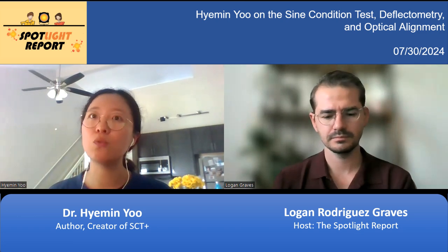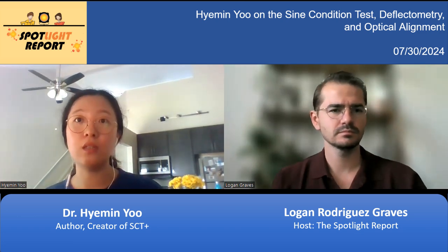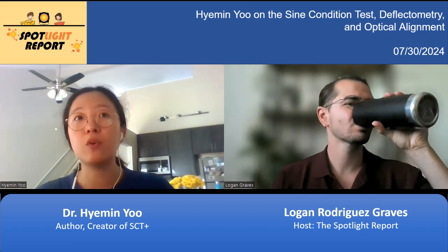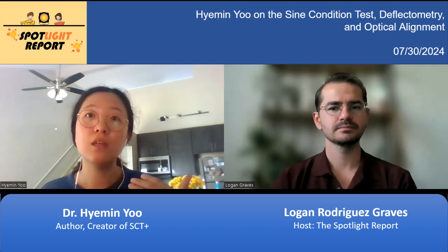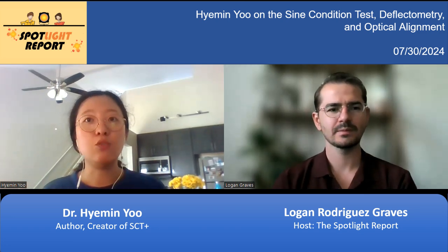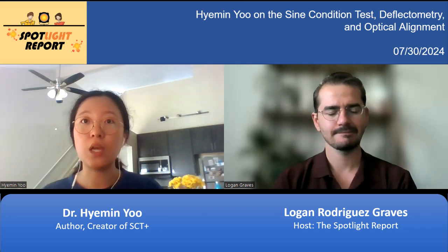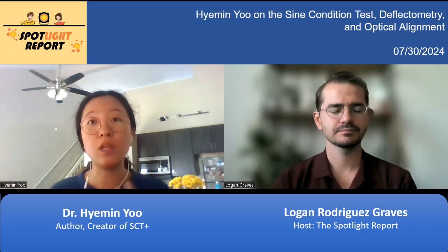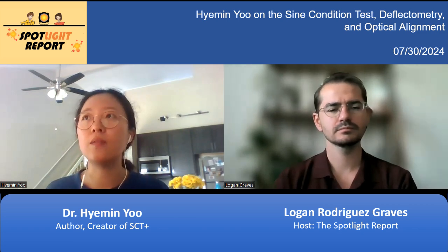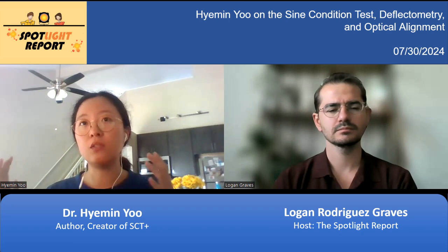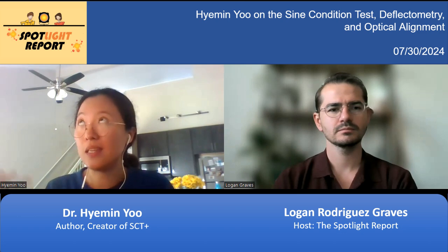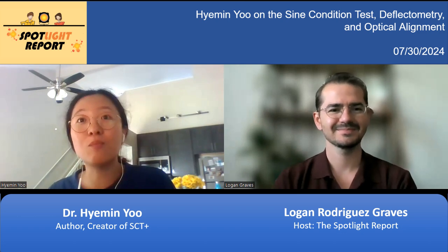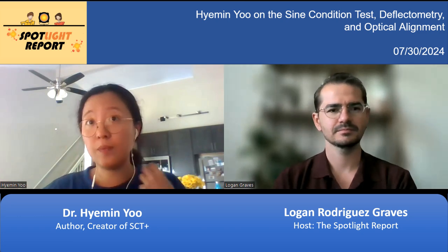So actually, we don't do any measurement during the alignment. So we don't know if the optical performance over the whole field of view of this optical system will be good or not. We just do some tolerance analysis before we choose alignment methodologies, and then we know, oh, within this range of tolerances we will have a 99.9% chance of having good optical performance over the field of view. So that's usually how we do alignment.